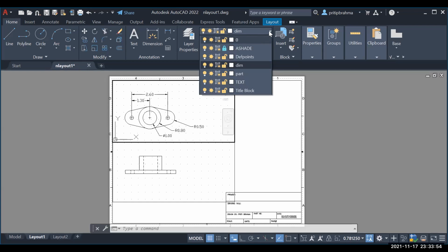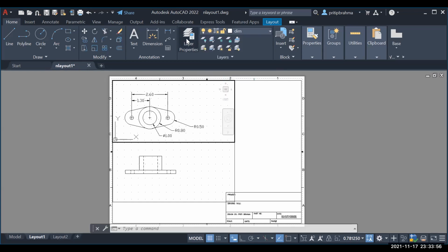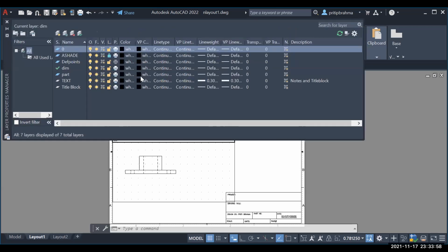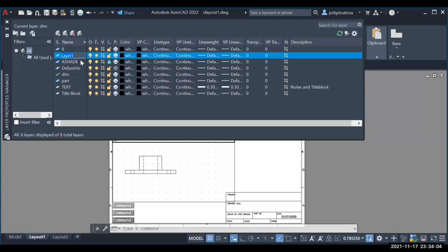All of these, I have to create a new layer. So create a new layer, and there's a naming convention for something that's not going to be plotted in ANSI, but create a new layer, and I can just call it the no print layer. And I'm going to make that not printable. So I can still see the edges, but not make them printable.